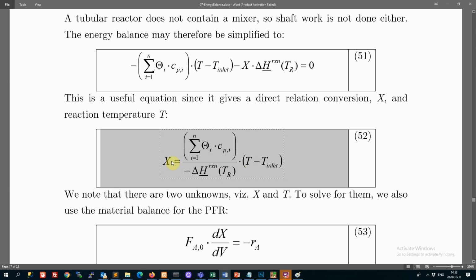So it's telling us that there is a given conversion. If we have 200 coming out and we put 100 in, then that prescribes already what the possible conversion is. So maybe it's 60%. So it's saying that for that reactor, if you achieve this temperature difference, then you must have converted to this extent, 60%, I just said. So that is a relationship for the adiabatic case.